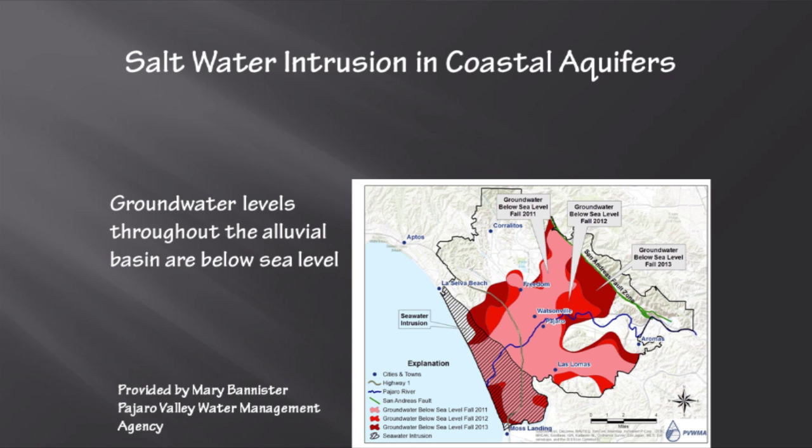So most recently, they measured that groundwater levels are about 30 feet below sea level over a large portion of this basin. And so when you take models and you simulate the effect of that saltwater intrusion moving into the basin, they're projecting that the saltwater is going to move well into the basin in the next 2 or 3 years, which is pretty scary, considering that this is a very productive basin and their production is going to decrease significantly if their water degrades that much.